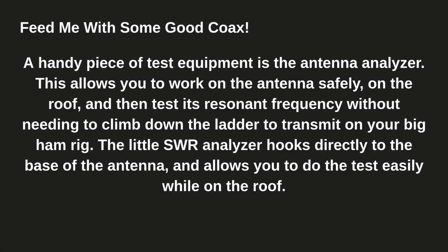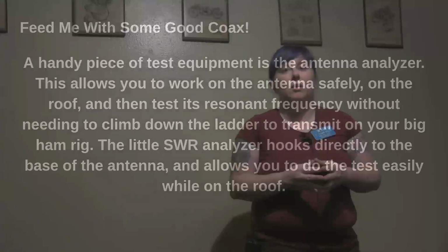A handy piece of test equipment is the antenna analyzer. This allows you to work on the antenna safely on the roof, and then test it. Well, if you're on the roof, still be careful. Then you can test the resonant frequency without needing to climb down the ladder to transmit on your big ham rig. The little SWR analyzer hooks directly into the base of the antenna and allows you to do the test easily while on the roof. I should have grabbed Donald's antenna analyzer to show you what one looks like.